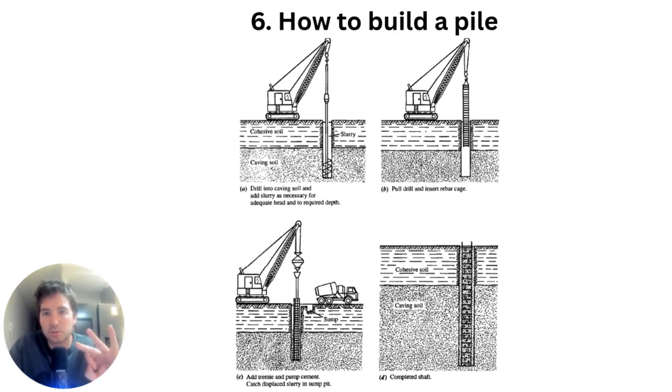There are three main ways to install a pile. I'll quickly go through the pros and cons of each of them. I'm also focusing on concrete piles here. You can use steel and timber, but concrete is, from my experience, by far the most common. Firstly, you can drive piles, and that is good because you don't have to wait for the pile to cure. It is already cured because it's precast. So in a sense, that's faster. The downside is it causes a lot of noise and vibration, so it might not be suitable in urban areas.